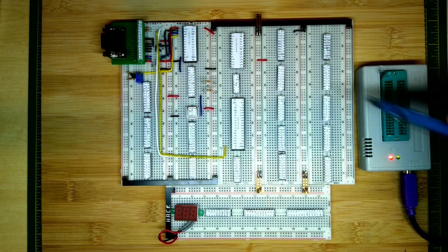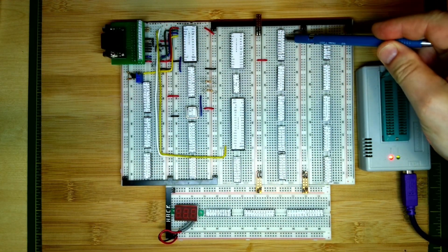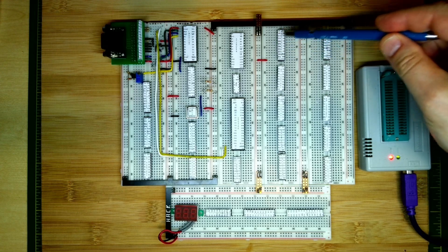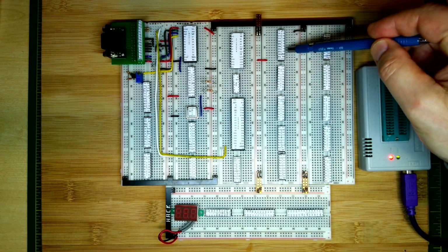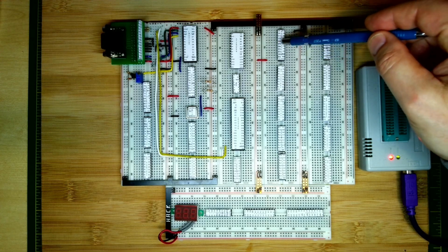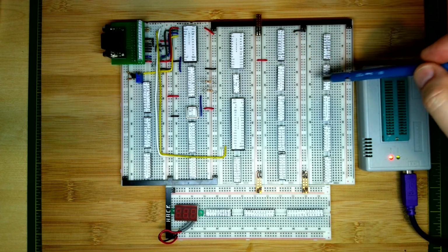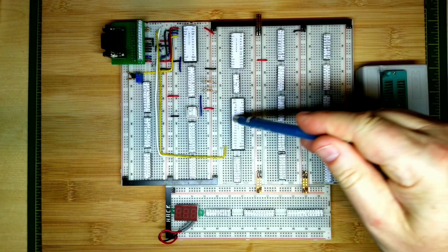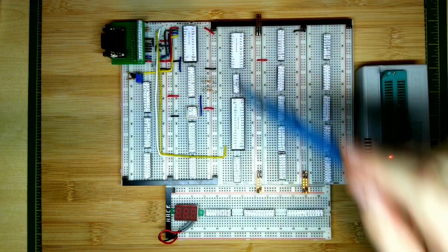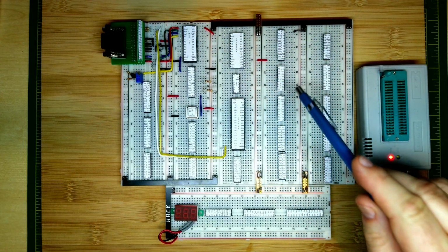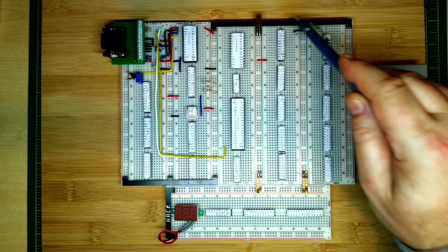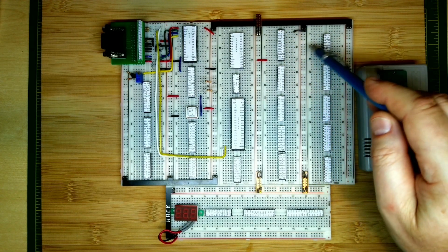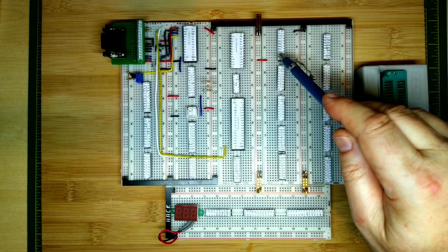Now we need to hook up the CGA IO decoder. So this is the thing that takes the addresses from the address bus and the IO read, IO write, and then produces all the various enable signals for the various latches and chips, so the CRTC and the video palette here. So we're just going to need to program this. We'll wire in the address lines and IO read and write when we actually put it in with the main board, so we'll leave those for the moment.